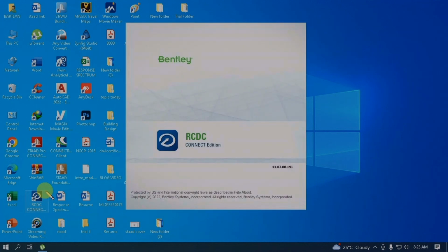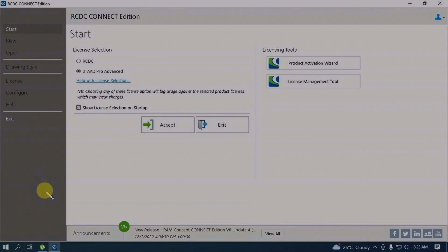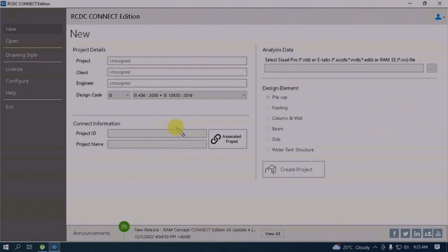After checking the beam shears, we now open again RCDC and proceed to next level. But it is always better to revisit the previous level every time the STAAD file is updated, for whatever changes made upstairs might affect downstairs.